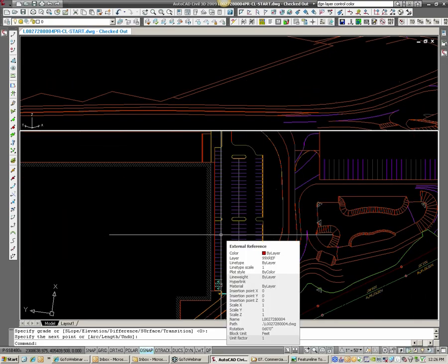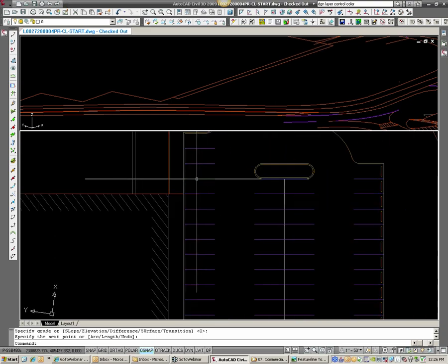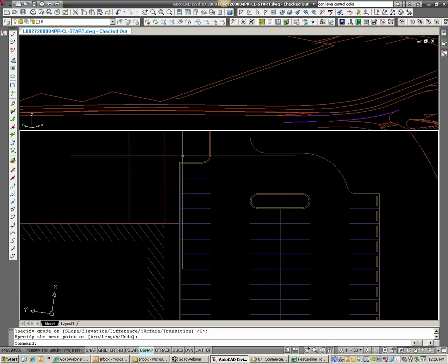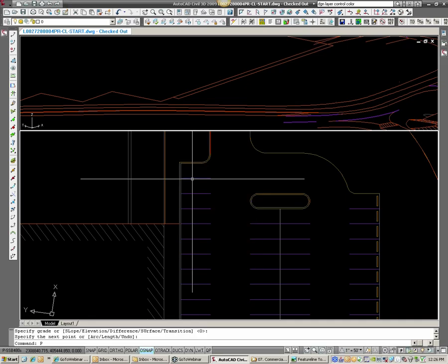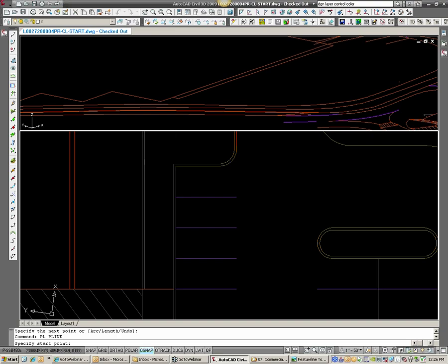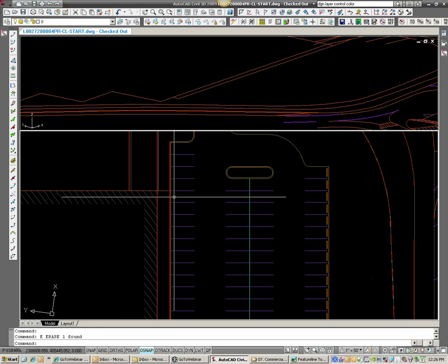Okay. Now moving right along, I want to extend that out. I want to hold that same elevation out to the edge of the parking lot here. So I'm just going to draw a simple AutoCAD line off the end here, just so I can extend that feature line across to the end of the parking lot. Just use the AutoCAD extend command. All right, so I've got the top back of sidewalk.